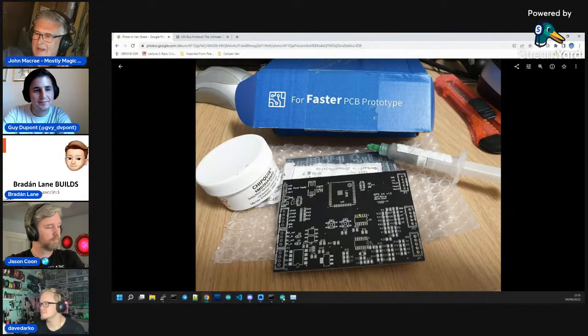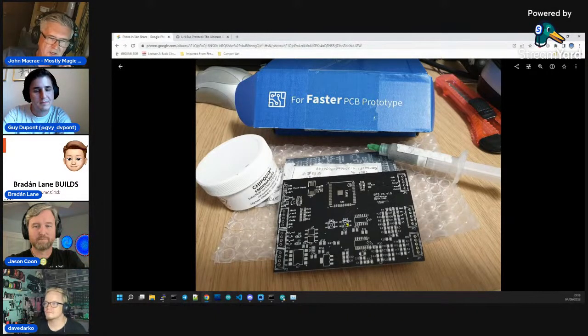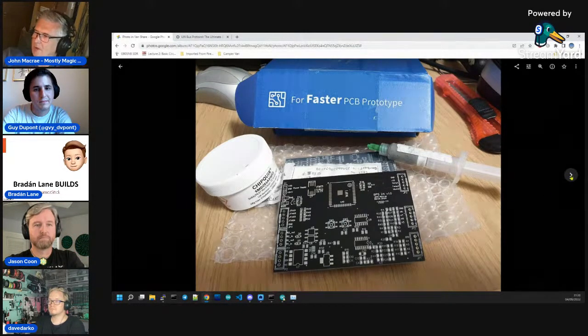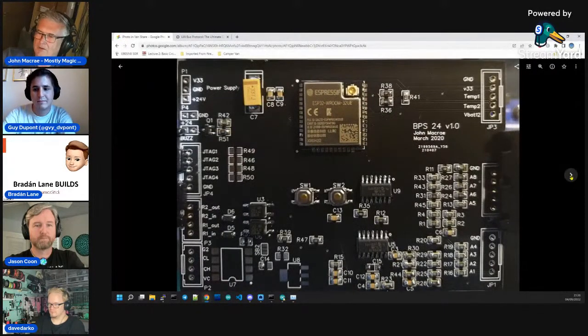So I homebrewed that with an ESP32 in the middle here, some rather old style slow ADCs, but since I only test the voltage every couple of seconds, that was quite adequate and a whole lot more stable than some of the more modern, much faster ones, like the ADS1115 that everybody seems to use. And to be honest, the Chinese knockoff ones are not very reliable. So yeah, we made that up, and I chose the